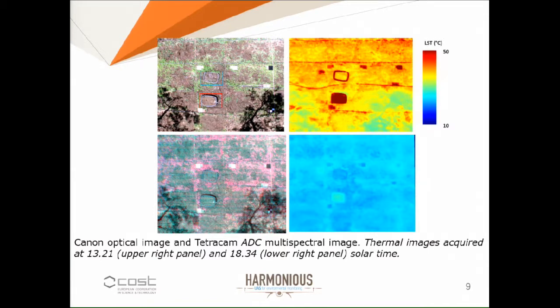And these shadows are going to change during the day, and we have seen that we need 2 thermographies, so this shadow has a different position during the day in the 2 images. Also, the vegetation is clearly visible, and the vegetation is another factor limiting the application of this methodology. That's because there is a hypothesis within the method that there is a linear proportionality between the net radiation minus latent minus the sensible heat flux with the soil temperature within 1 day of acquisition.